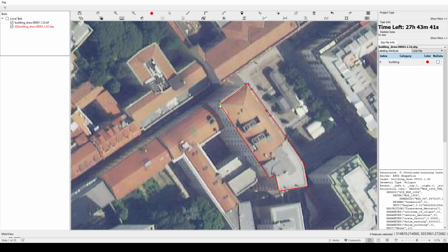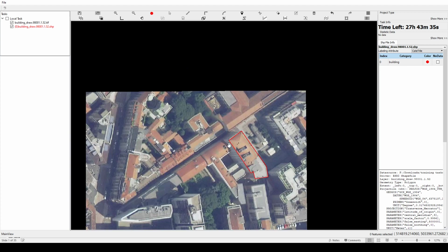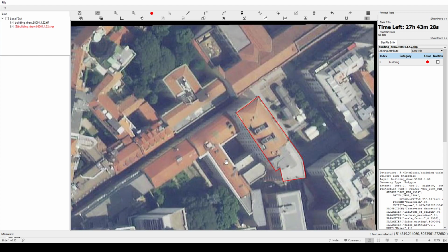Okay, 3, and then I'm going to set the vector. Why would I set the vector? Because obviously these are other buildings and this is another building, but they are attached, so they need to have one vector. So I select that one. I press Control, and then I drag all the way to the bottom. Don't worry, it locks the vector.